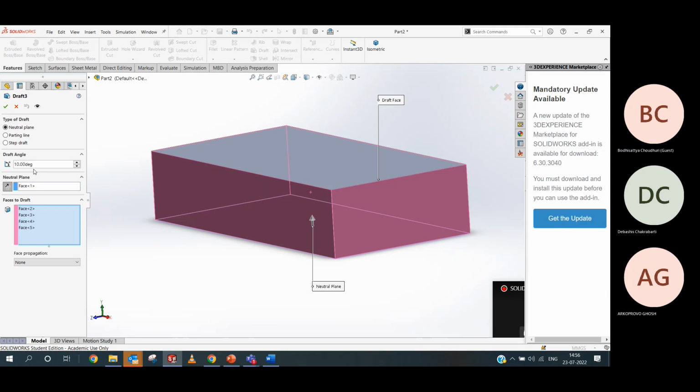No, that is available in some features like the extrude feature and revolve feature. Oh, okay, I got it. Yes, the draft feature is there, but it is a different option, a different feature. It's apart from extrude, revolve or sweep. It's totally different. We can separately define here the faces to draft according to the angle parameter.